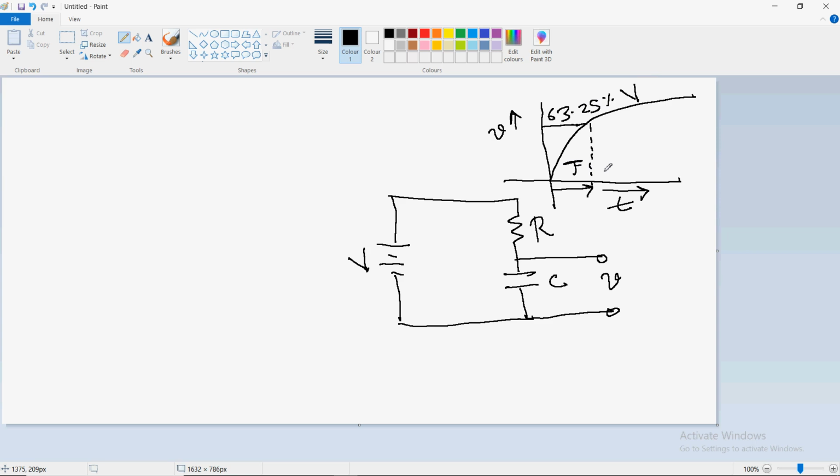Okay. So mathematically, what is the value of time constant T? T equal to R multiplied by C. For simulation purposes, we will select R equal to 10K, and C equal to 100 microfarad. Please note that these R and C are very practical values. That means such components you can get from the market very easily.